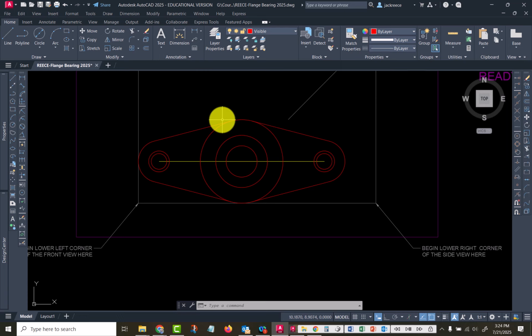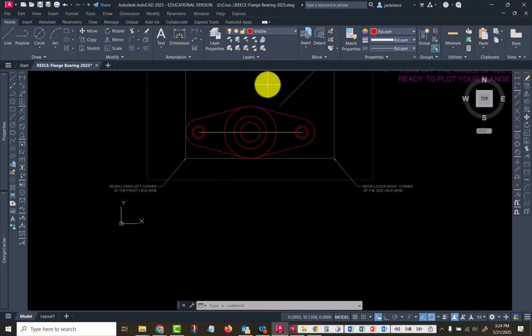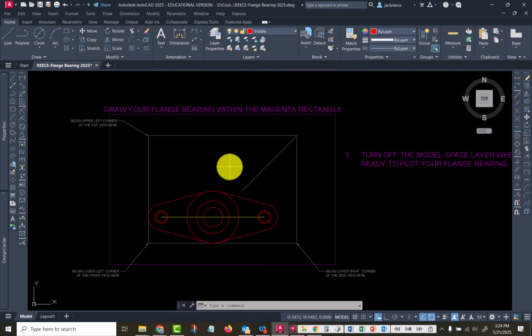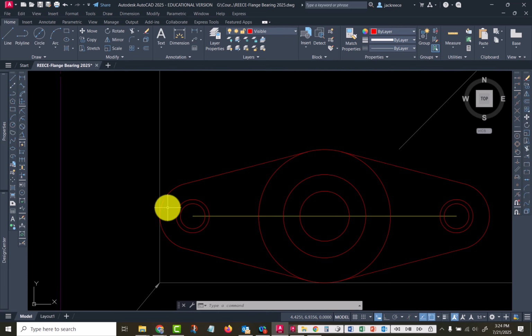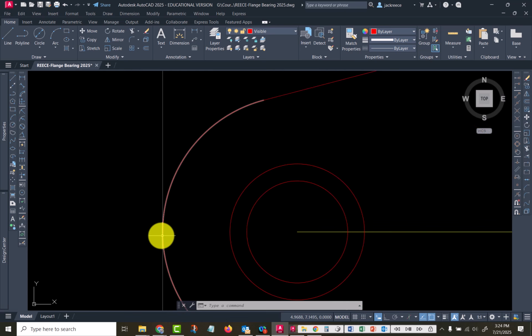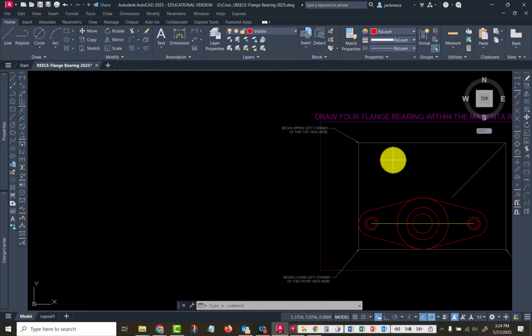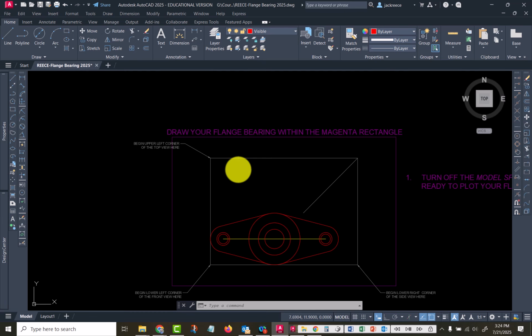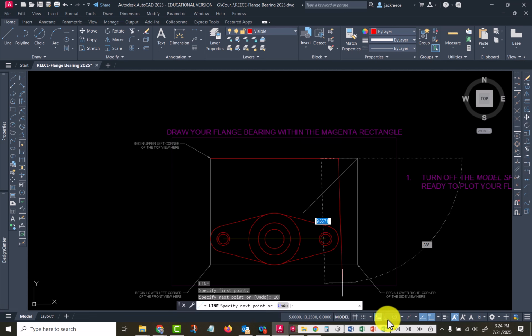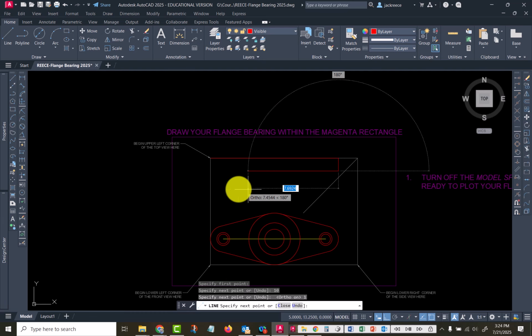And we're gonna want to talk about center marks specifically as we're going through this. So let's go to our top view, and because we started over here on the very edge, because that's why I gave you the offset from, let's draw a line from this corner. We're going to go over 10 inches. That gives me the rear of the object. I can turn my ortho back on. I'm going to come down 1 inch, which is the thickness of the base, go back 10 and close.